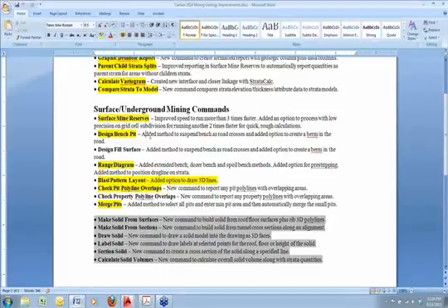And so for this version, they've added options to suspend the bench or to pinch the bench width down to 0 thickness as it intersects the road, the automatic ramp or road generated when you build the pit. In addition to that, they've added an option to put the berm automatically onto the side of the ramp or the road, which has never been done in the command itself. It was always done as an external portion of the civil or road network. So now it's all included in the surface mine design bench pit. So let's go ahead and try that.